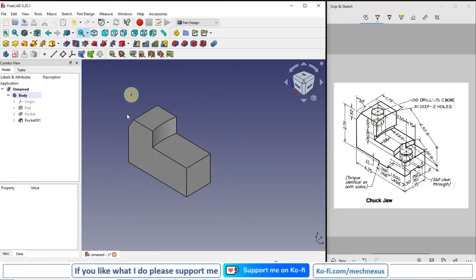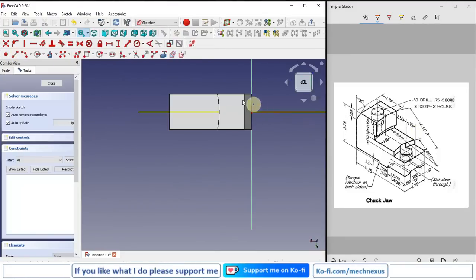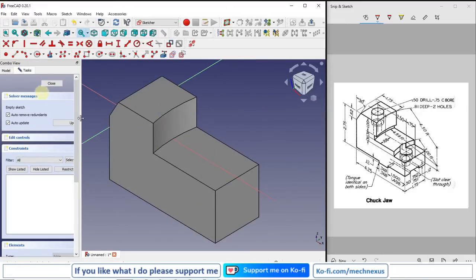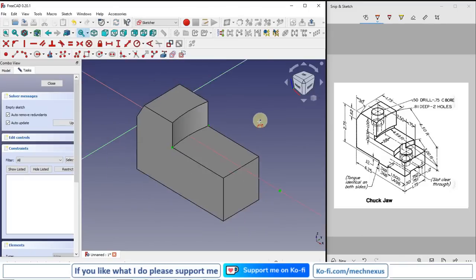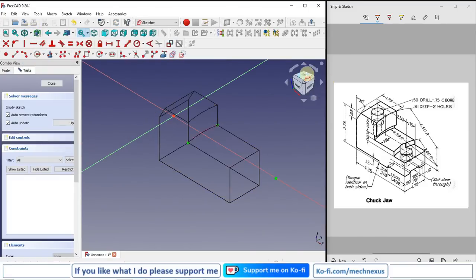Now on this surface we will make this cut of radius 4.69, which has the same center as the cut which we have made here. So I will select this face and I will say sketch, and I will switch to the isometric, and first I will require this arc, so I will project it and I will switch to the wireframe here.